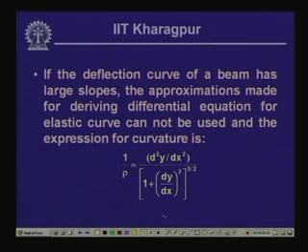Now, in this particular case, while deriving the equation for the elastic curve, we have considered that the deformation is a small one, and thereby we said that the axial axis of the beam, when it undergoes deformation, does not stretch; the length dx remains dx.